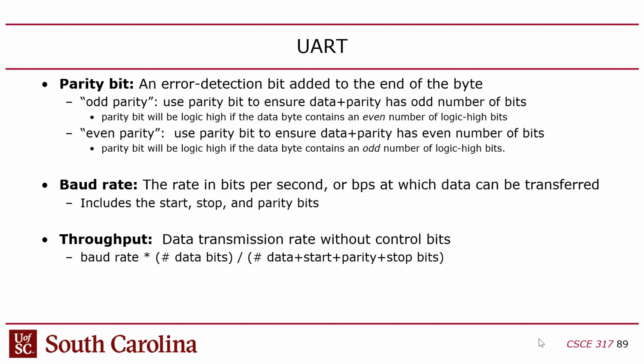Yes? So why is it still a byte if there's 11 or more bits in it? That's what I don't get. So the byte is the payload. So the start bit and the stop bit and the optional parity bit are extra. And actually, there could be more. You could configure the channel with more than one.